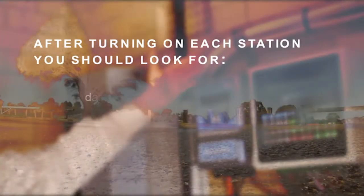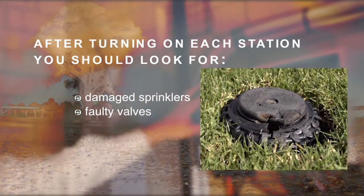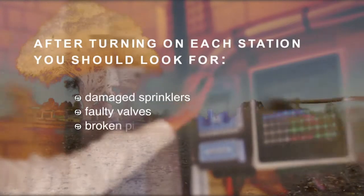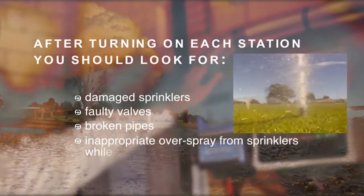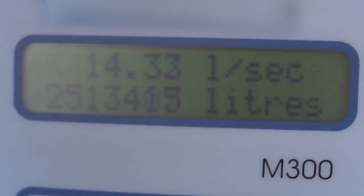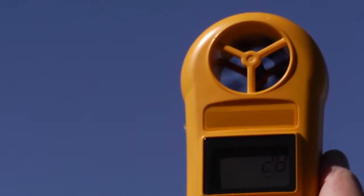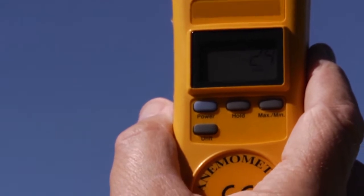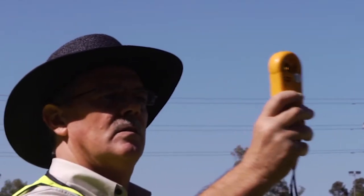After turning on each station, you should look for damaged sprinklers, faulty valves, broken pipes, and if there is any inappropriate overspray from sprinklers while operating, for example, throwing water over a roadway. This is a good opportunity to record the pump operating pressure for each station and to check that the water meter is operating. If certain things need to be fixed, then the assessment test may have to be delayed for a few days. It's always better to get things right before you start to do the assessment.